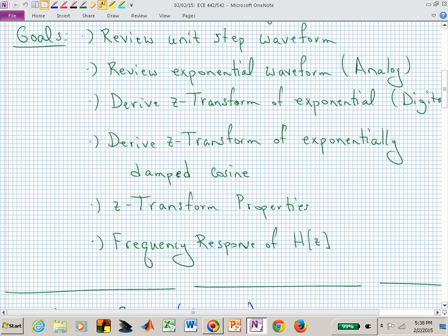Now, with that clue, where do you think we will be associating sinusoids, not damped sinusoids, but pure sines and cosines in the complex Z-plane? On the unit circle. The imaginary axis in the S-plane now maps onto the unit circle of the Z-plane. And you can see that.